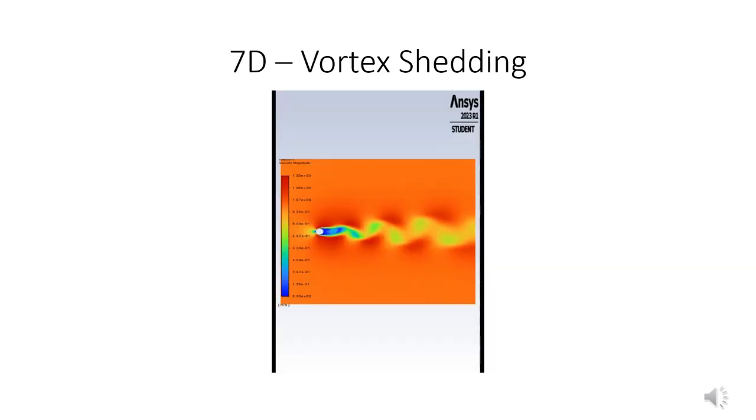As can be seen from this video, fluid flow around a cylinder with a Reynolds number of 100 creates what is known as vortex shedding. This is where a low pressure region occurs behind a bluff body, an object in which there is a large amount of separated flow, in the form of a wake. As fluid passes around the cylinder, it recirculates in the wake, creating wave-like velocity patterns that exit off the body. These vortices, due to their varying velocities, cause vibrations on the objects they pass, which can potentially match the natural resonance of the objects. These vibrations can then seriously damage the bluff body and should therefore be accounted for in their construction or reduced.